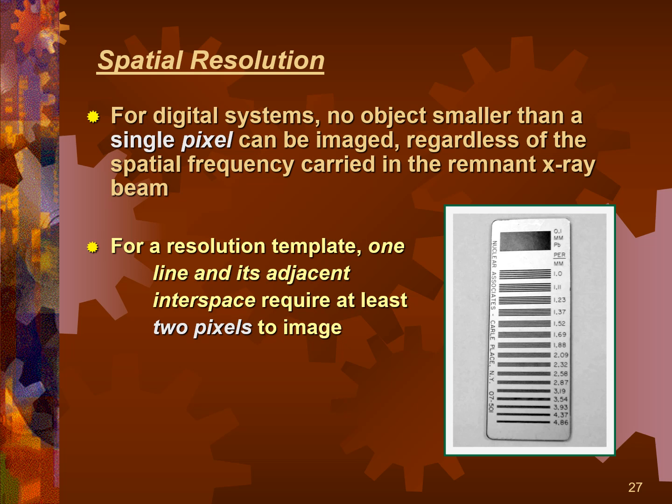Versus if I go to the 2.09 line pairs per millimeter, now some of the white is on the first pixel rather than on its own pixel. And so the colors are blended together. And so our ability to transfer the frequency from the actual object to a representation, to an image, has broken down. In other words, we've lost modulation transfer.